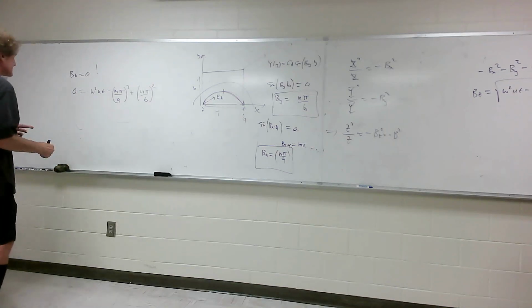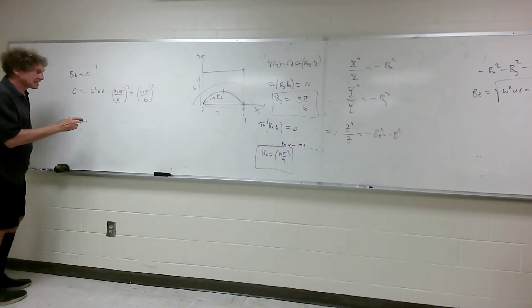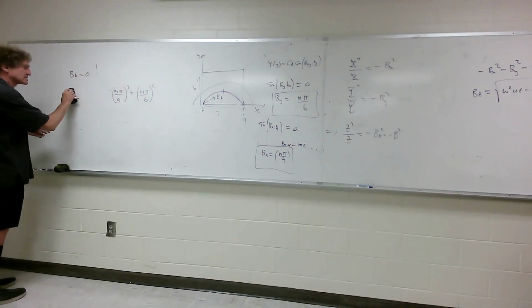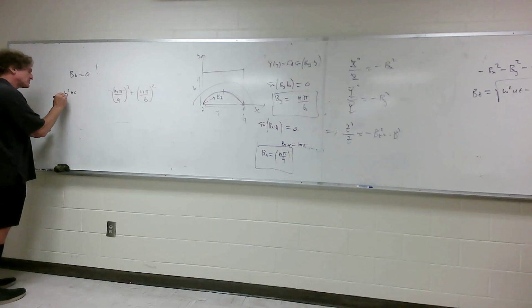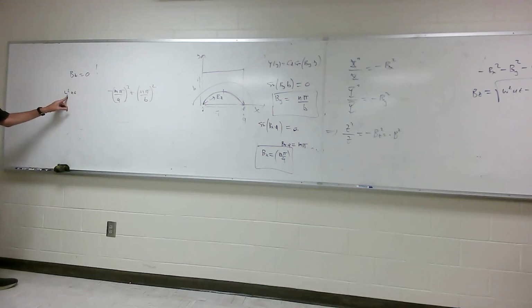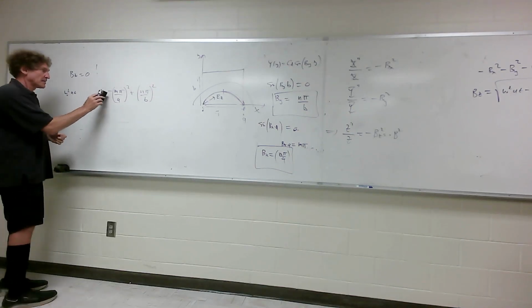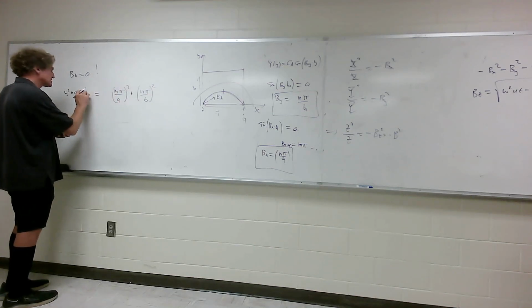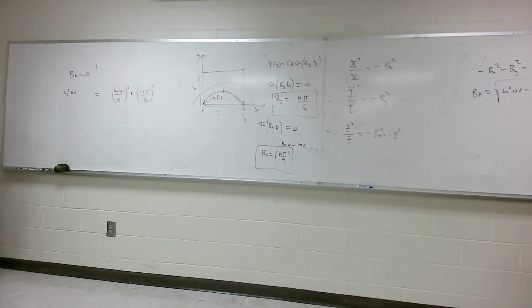So when I take a look at this, why don't I take omega to the other side and get rid of these negatives, so I have omega squared mu epsilon. We call this the cutoff frequency, so you can put a little c here. And this is going to be equal to this plus this. I just rearranged the equation. Are you with me, class? Please, this is real important. You have to get this.